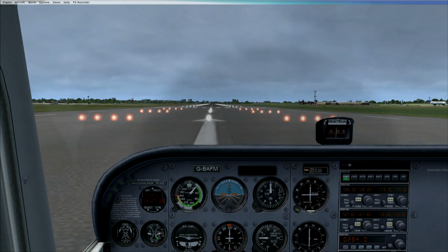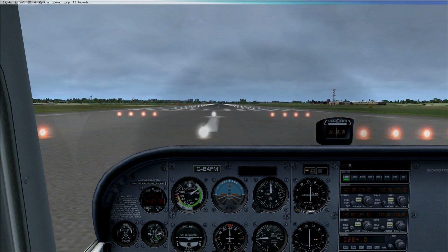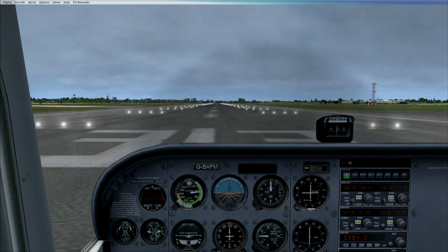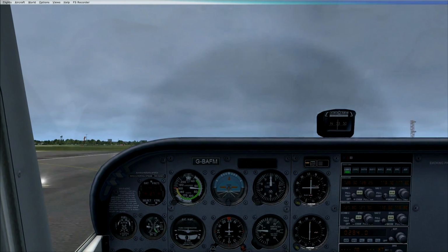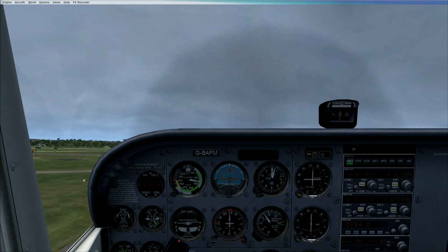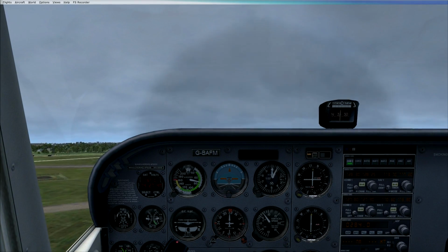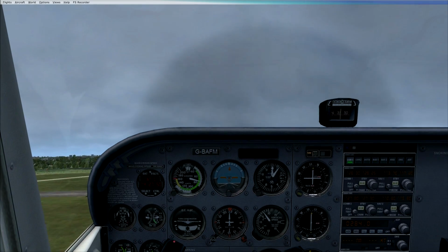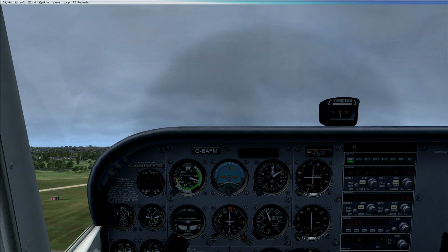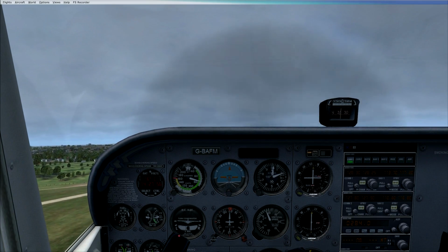So first thing we're looking for is on our airspeed. We're going to rotate at 65 knots, give ourselves a good margin above our stall speed. So there's 65 knots now, and bringing the nose of the aircraft up. We're trying to establish ourselves in a 75 knot climb, which we've got there or thereabouts. So now I get an opportunity to trim the aircraft rather coarsely, but there we go, and we've got ourselves established nicely in the climb.